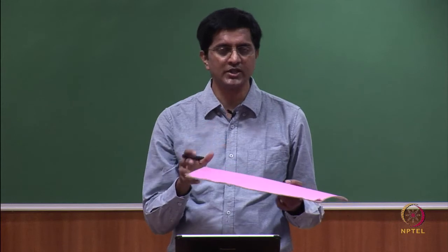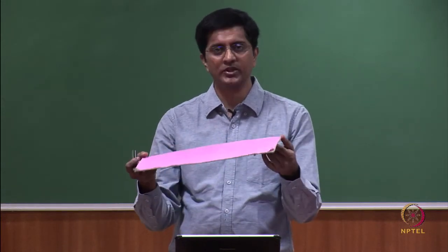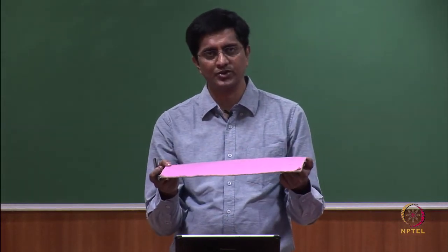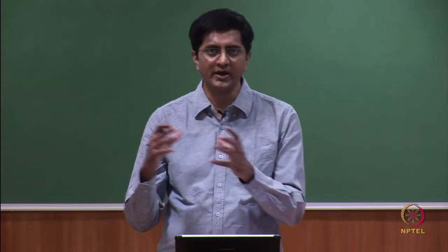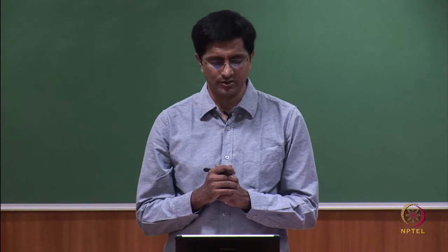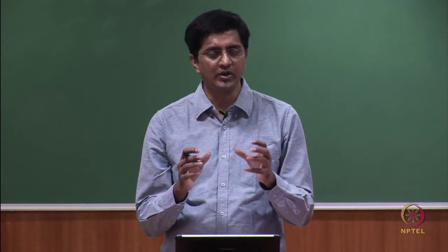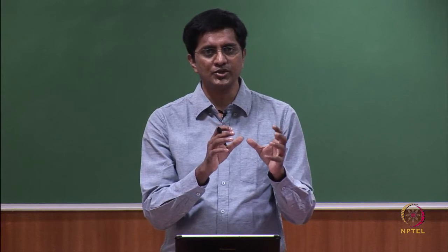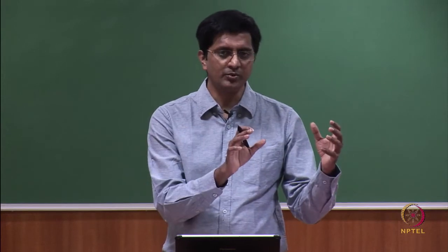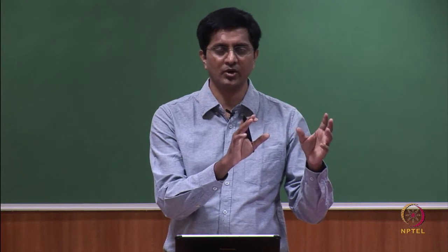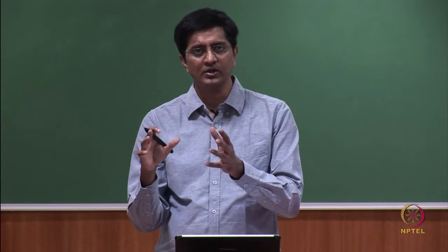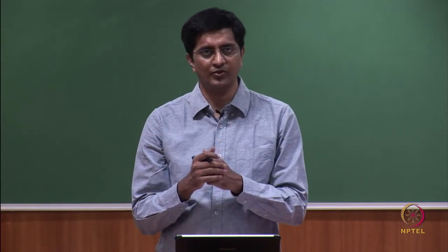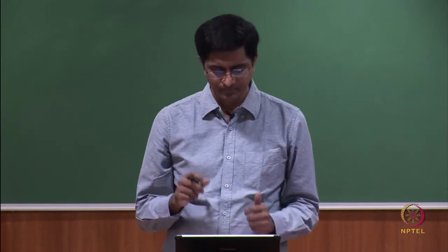It is not to say that even for a simple thing like a rectangle we should follow this procedure, but we are trying to demonstrate a new principle which can be applied for any complex object. So, the idea being we will break down the procedure into two steps. In the first step, you make the object in a very simple orientation where you can draw the front and top view very easily, and then use that information to develop the actual problem where the object is inclined.